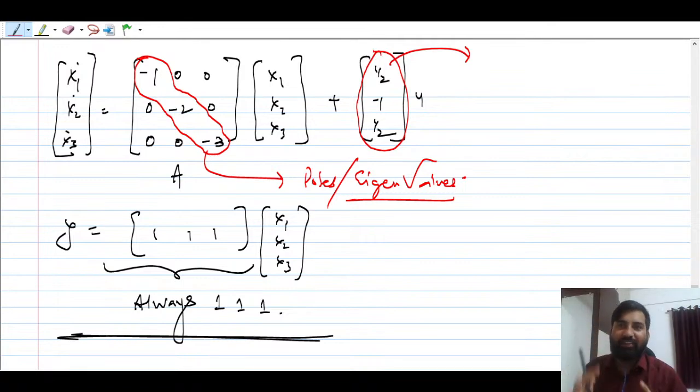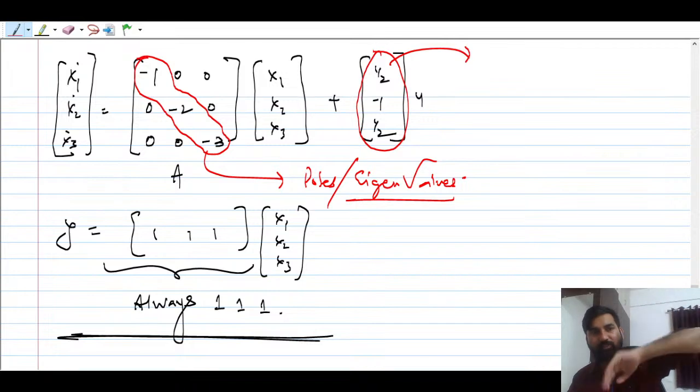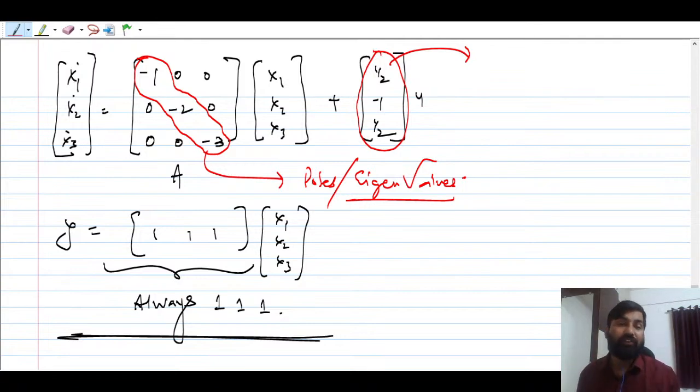So I think the A matrix you can directly obtain without doing partial fraction expansion, but after factorizing the characteristic equation you can get all the diagonal elements and obtain the A matrix. But how to obtain this B matrix? You have to do the partial fraction expansion, right?